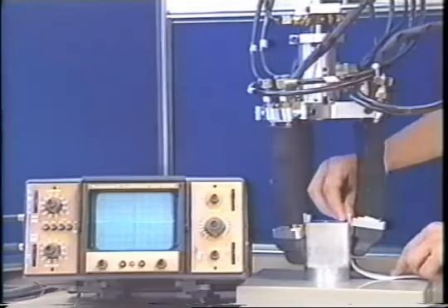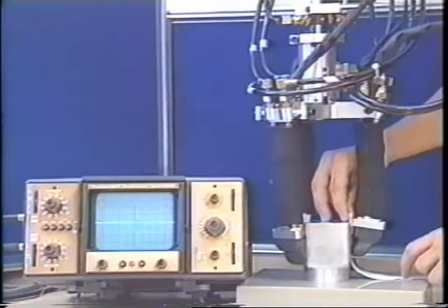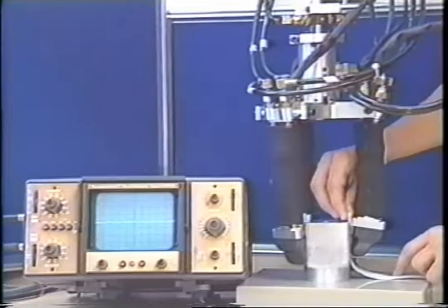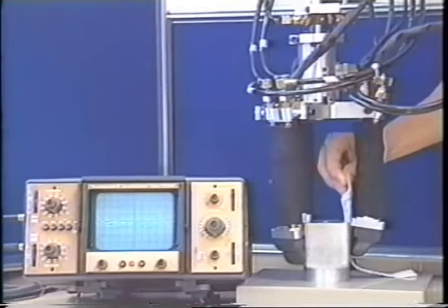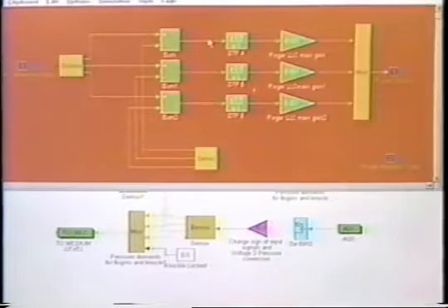Slip sensing uses a PVDF piezoelectric strip embedded above the skeleton. Slipping vibrations are transmitted through the elastomer and converted to an electrical signal. Using the MATLAB real-time extensions, closed-loop control of finger and hand have been investigated.